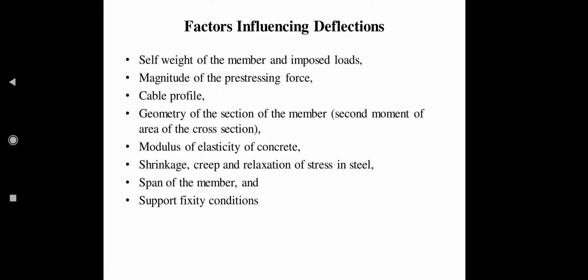Cable profile. So cable profile should be properly provided. If we provide a cable profile the same as the bending moment diagram, then the deflection and the bending moment will be 0. Geometry of the section of the members. So geometry of the section will also play an important role in controlling the deflection.